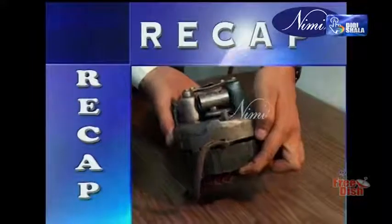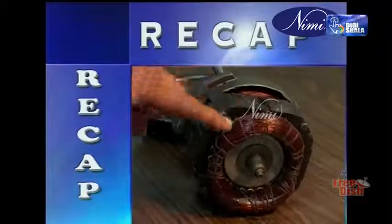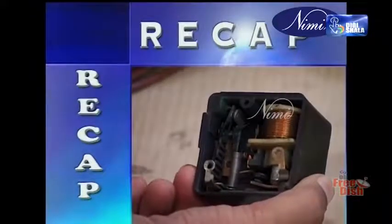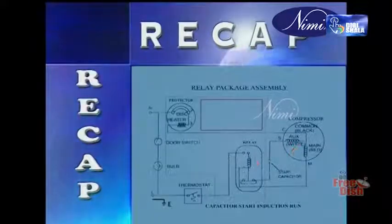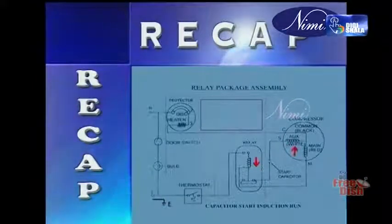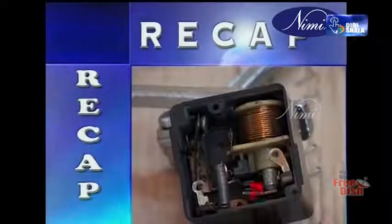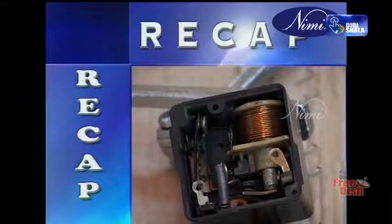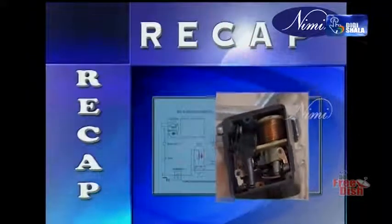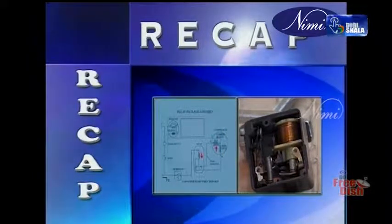Refrigeration capacity. Removal or absorption of 12,000 BTUs per hour, or 3024 kilocalories per hour, is equal to 1 ton of refrigeration. Compressor motor windings. A single-phase compressor has 2 motor windings, the start winding and the run winding. The relay allows the current to flow through the starting winding of the motor until the motor reaches about 2/3 of its rated speed. At this stage, the current flowing through the relay coil gets normal, magnetic intensity goes down, and it is not able to hold the weight of the plunger. The plunger gets down due to its weight, then disconnects or opens the contact point, which opens the starting winding circuit.